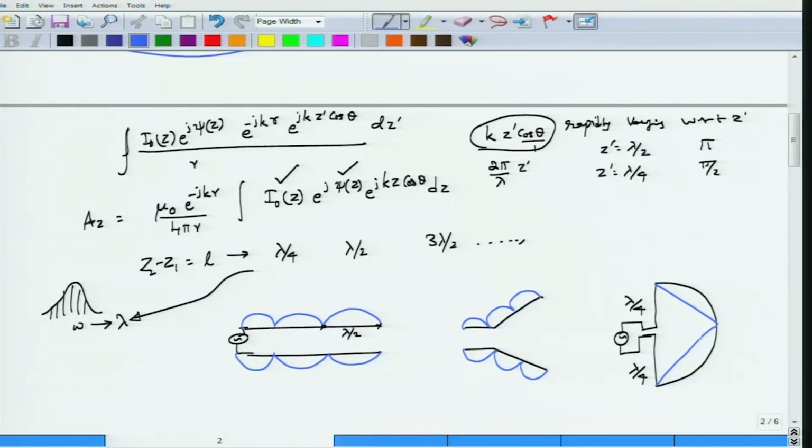For example, there is a triangular current distribution, and if your antenna length increases, for example, instead of this lambda by 4, total giving you a lambda by 2 length, if you had a lambda antenna, then you have lambda by 2 here and lambda by 2, for which the current distribution would be twice of this one. So, hopefully, I have captured it correctly, but maybe I am not capturing it completely. But the point here is that the type of current distribution depends on the antenna length, and it is one of the most important problems to actually specify this current distribution.